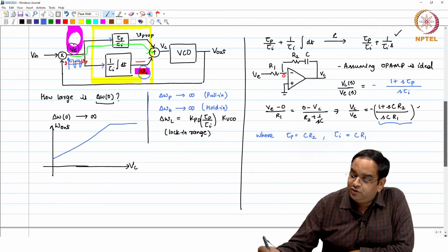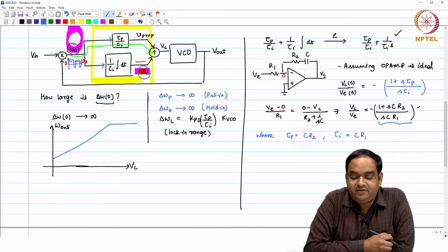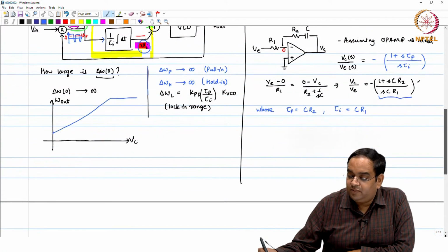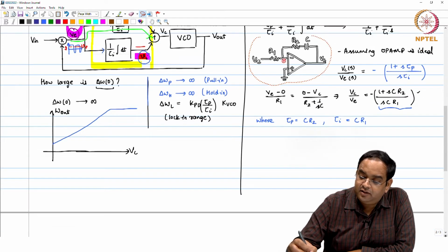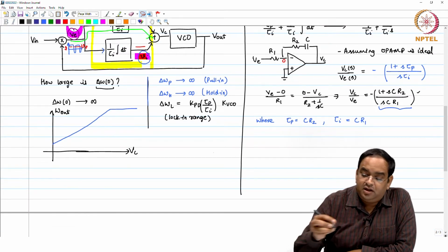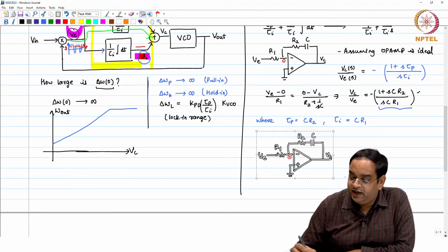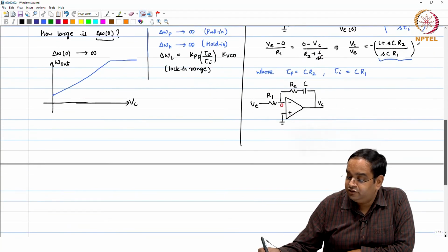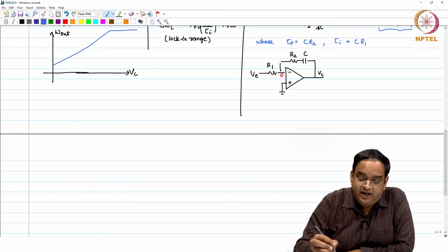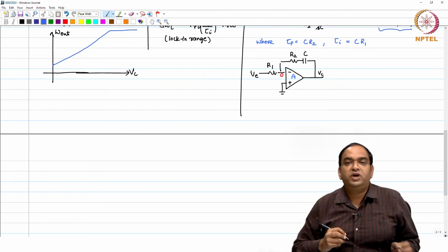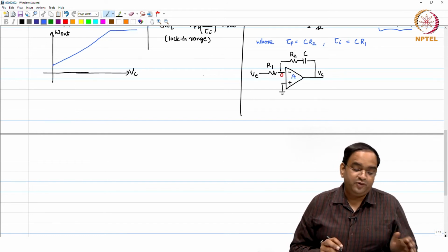Given this loop filter, you can very well add this loop filter here and everything seems to work. The problem arises because this loop filter which you are seeing here does not have an ideal amplifier, the amplifier happens to be non-ideal. So, we will introduce only one order of nonlinearity here, that this has a gain A. This is even a very simple nonlinearity, that the gain is fixed across the frequencies